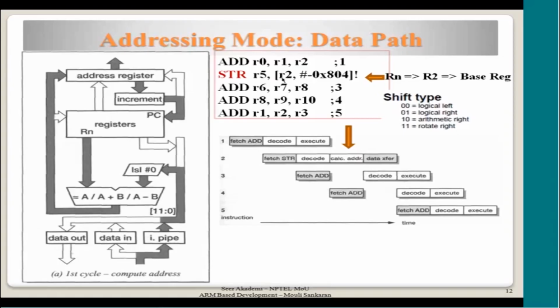That is why, until the memory cycle is completed, this register is not modified. Though it says, hey, I want to overwrite the value, it waits for the memory cycle to complete and the data to come from the memory, or for the data to be written into the memory without any issue. Then in the next cycle, once the transfer is done successfully, you can update the value.